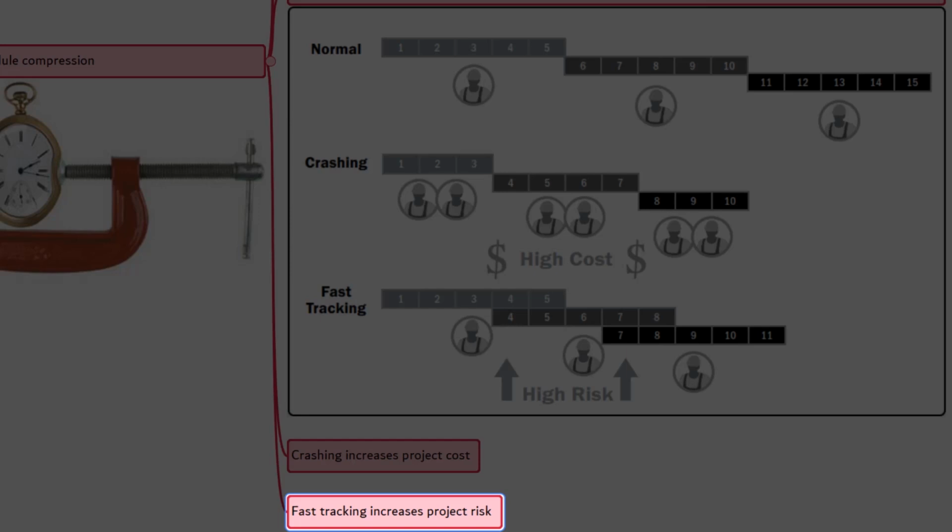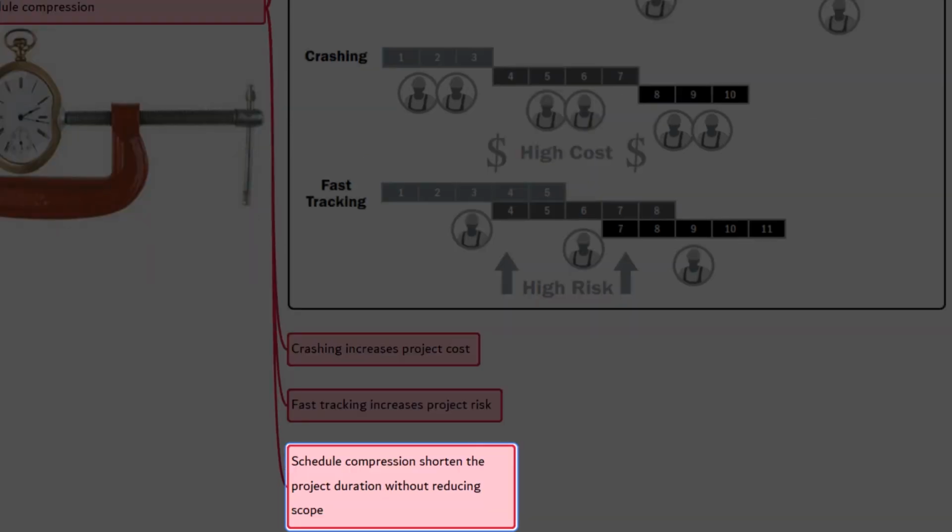In case any major changes are to be done in the construction to match with the aesthetic part of the building, then you may end up doing rework. It could be small or it could be big. It completely depends on the architectural drawing. But you already took the risk and proceeded. Here, you achieved time but added risk. So these schedule compression techniques are used to shorten the project duration without reducing the scope. Obviously, they are done to meet the schedule imposed due date or milestones.